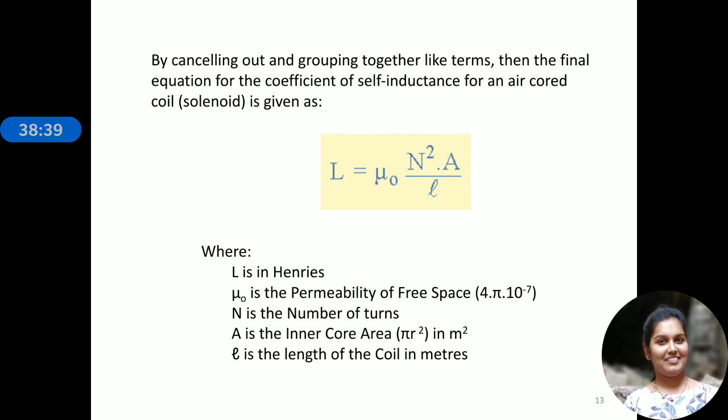So if the inner layer of the core is made up of some ferromagnetic materials such as soft iron, cobalt or nickel, the inductance of the coil would greatly increase, because for the same amount of current flowing through, the magnetic flux generated would be much stronger.